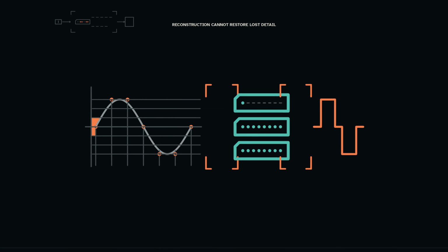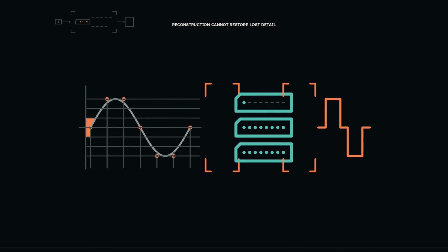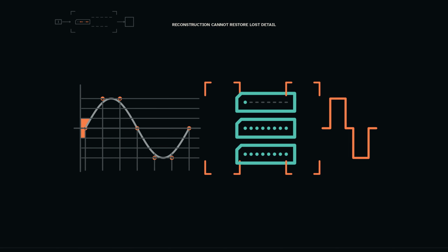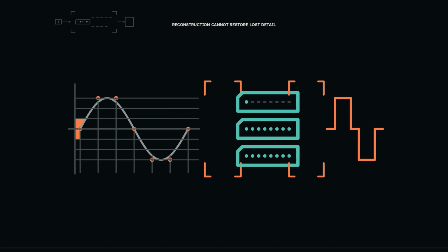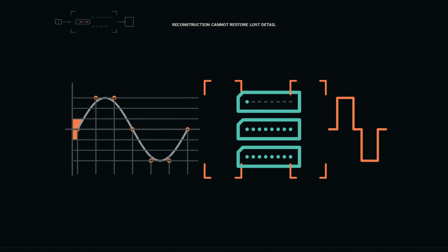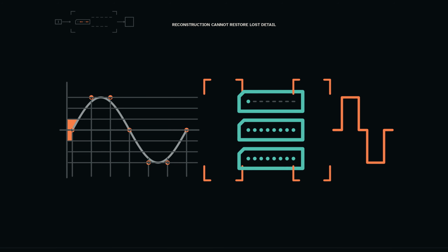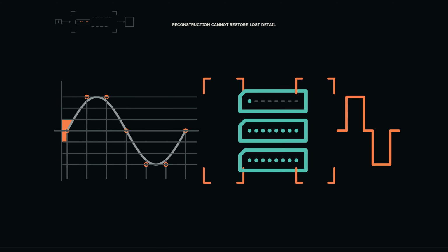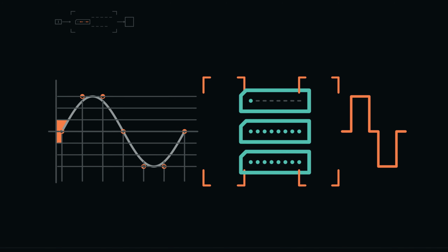Identify the possible losses. Sampling can fail to distinguish changes that occur between chosen times. Quantization replaces a measured amplitude with one available code. Values outside the converter's input range may be clipped. Noise and component limits can disturb the measurement. Later, compression or processing may discard further detail by design. Naming these boundaries does not make digital representation unreliable. It states exactly what the representation can and cannot preserve.